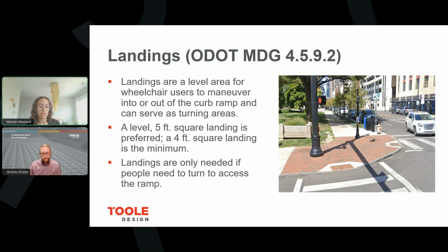You might have other situations where the sidewalk and the curb ramp are both in the same direction, and so no turns are necessary, and then a landing would not be required, although a clear space at the bottom might still be required.